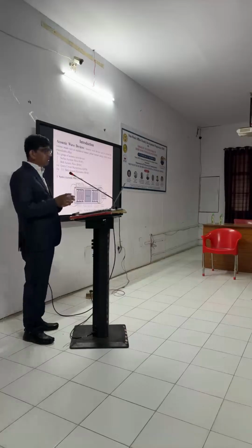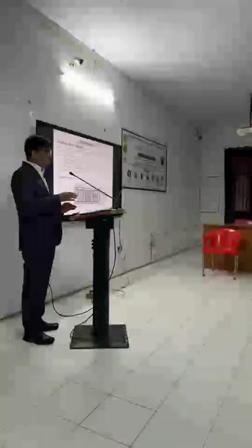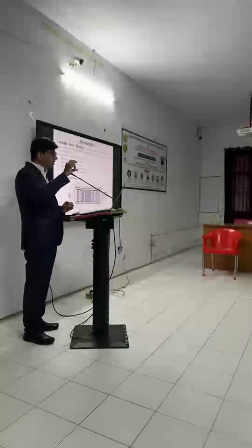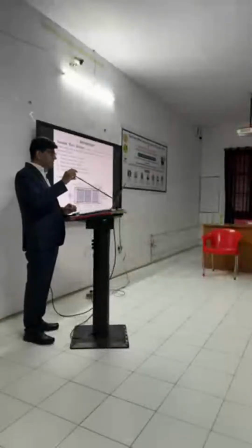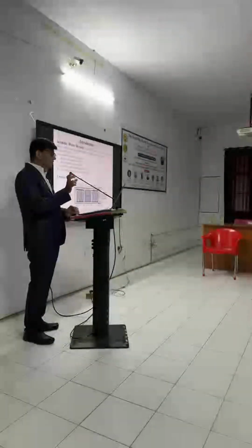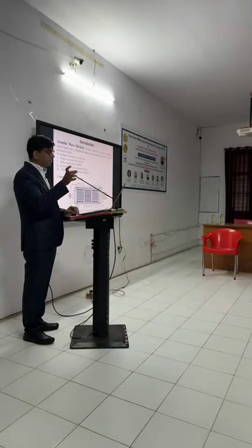So what is the inverse piezoelectric effect? Basically, once we apply a voltage to a device, stress is generated in the piezoelectric layer, and due to this stress there is mechanical vibration in the device, and due to this mechanical vibration it will resonate at a particular frequency. This frequency depends on our piezoelectric layer. We will see how the resonant frequency is calculated for this device.